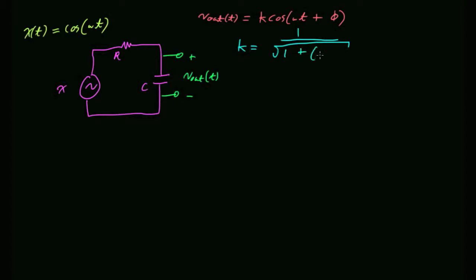Okay? All right, and what about the phase angle? Do we get a formula for the phase angle? Minus inverse tangent, omega RC. Just omega RC. Beautiful. Okay? Now, I claim that everything you need to interpret this as a low-pass filter, we agreed this is a low-pass filter, right? We've talked about it like 17 times now, I think.